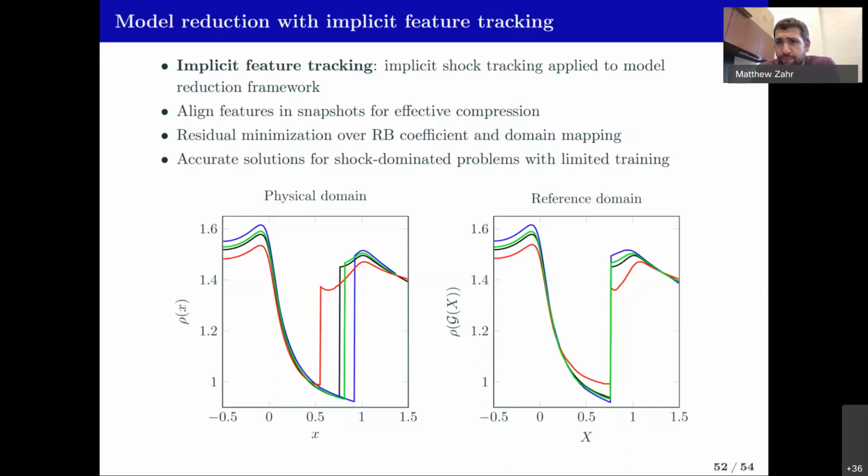If the method of lines approach would work, meaning your shocks aren't doing crazy things, bouncing all over the domain, then that would be the easiest and probably go-to option. If you have really complicated things where a shock forms, bounces off something, intersects, and goes all the way across your domain, then I just don't see a solid path forward with the method of lines. So that's why we're investing in the slab-based space-time approach for that.